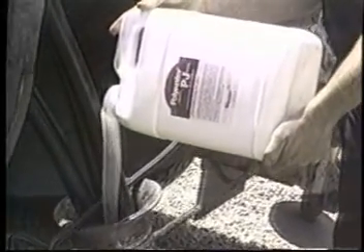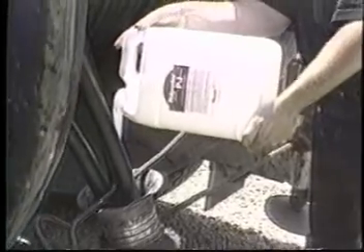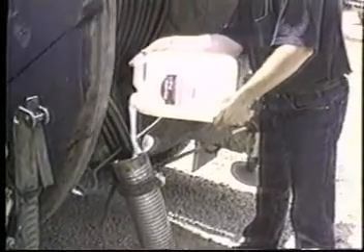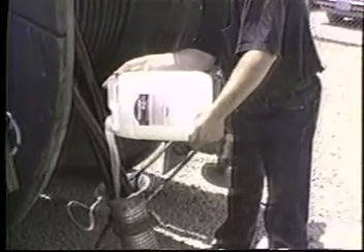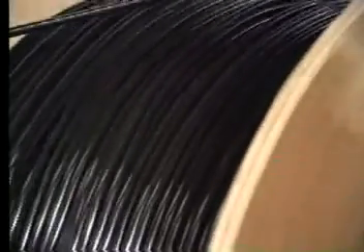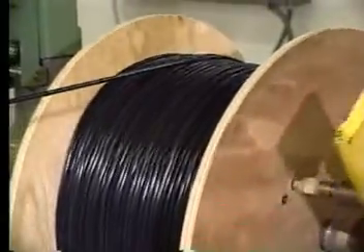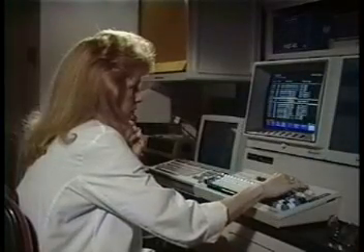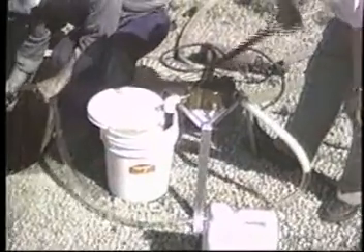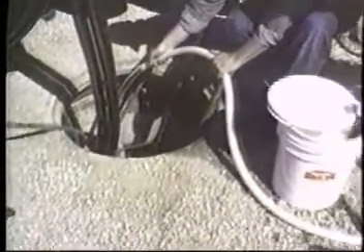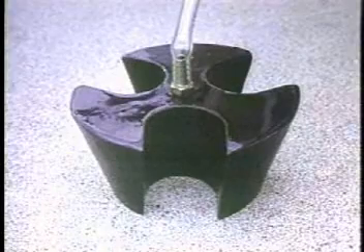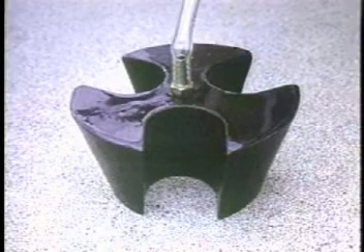When choosing a lubricant, remember that it must be compatible with the cable jacket, duct materials, installation method, and must be rated for the ambient temperature during installation. Some cable manufacturers maintain lists of appropriate lubricants for use with their cables. In addition, sets of pulling equations or user-friendly software is available to calculate tensions and lubrication parameters for your installation. Lubricant manufacturers provide application equipment ranging from hand pumps and T-style applicators to various styles of lubrication saddles to make the job clean, easy, and efficient.